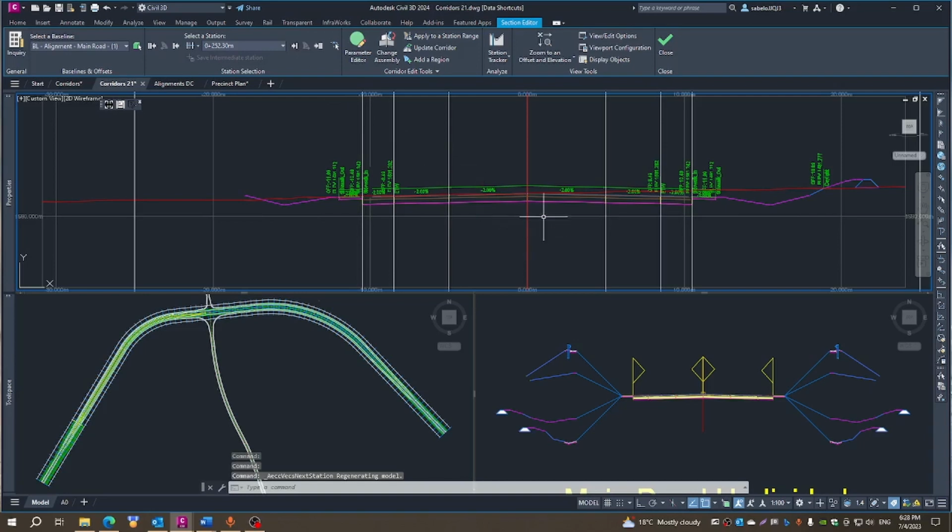Okay. At this point, we're going to start from here on. The island is going to start to be introduced, because you will find now that the lane is starting to be a bit wider, so the painted island will start to creep in. Maybe the painted island will be about there, because our lanes are about 3.5, and you can see these inside lanes are a bit wider, and that's because from about here you'll start to have a painted island, which will then reduce these lanes.